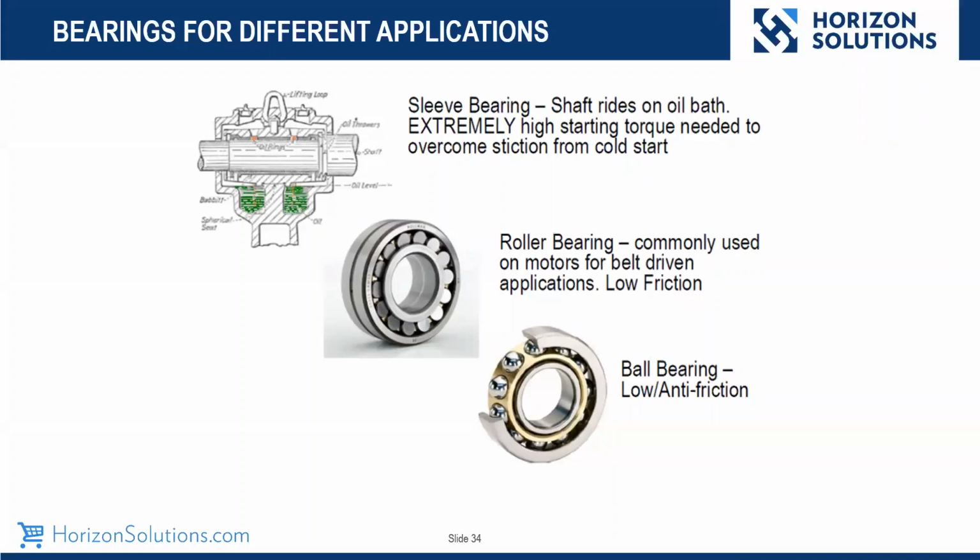And ball bearings, you will see they have the lower anti-friction versus some of the other styles, obviously, right? Like above. The other thing too is these are used predominantly on smaller motors, and they work really well. But if you have an application on a smaller motor where you have a belt or even a chain where it cantilevers over, the roller bearing style is definitely the thing that you want to use. It will stop any premature bearing failure that you have. Next slide.